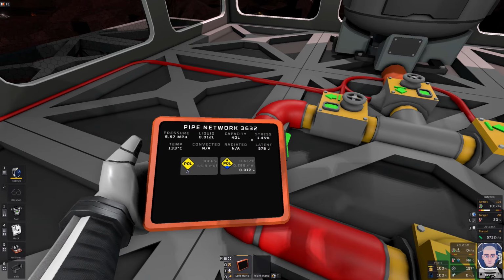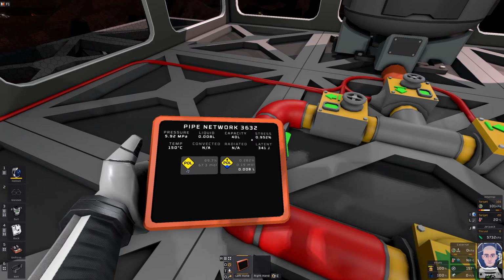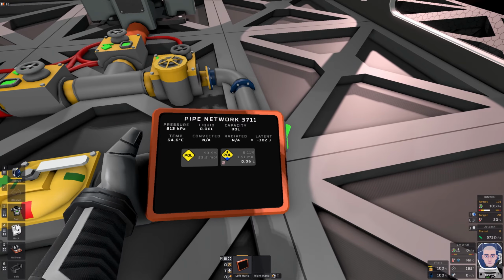All right. So the pressure is high enough, as you see. Now we generate liquids, and the temperature is going up. And as the temperature goes up, the pressure required goes up. The temperature will go up to high enough that we will no longer generate liquids. So we notice if the temperature gets too high, around that 150 mark, we can't have any more liquids. So we'll shut down at that point. And we're just about to hit that point. And then liquids will stop. And this side is down to 64.